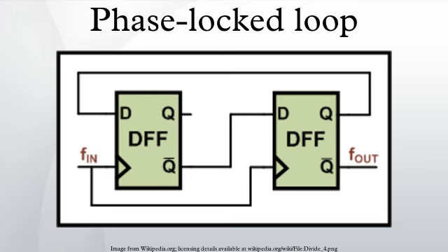Applications: phase-locked loops are widely used for synchronization purposes. In space communications for coherent demodulation and threshold extension, bit synchronization, and symbol synchronization. Phase-locked loops can also be used to demodulate frequency-modulated signals. In radio transmitters, a PLL is used to synthesize new frequencies which are a multiple of a reference frequency, with the same stability as the reference frequency.